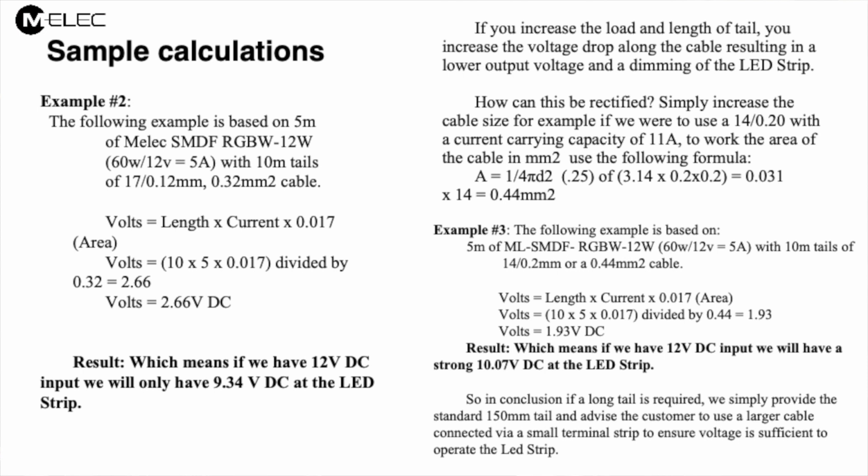It's too low. The LED strip will not be brilliant. You won't have your clear, crisp, sharp colours. You'll have very dull, and it'll look a bit milky. So make sure you've got 12 volts, a good solid 12 volts there. There are some more sample calculations that we've done for you.